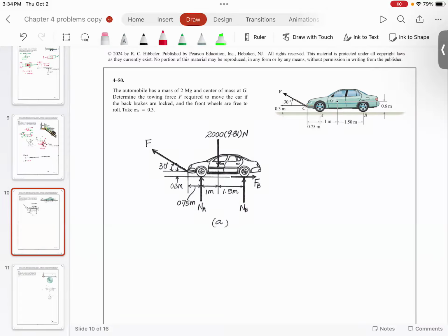And understand, I don't know if you have seen the older vehicles, older cars. There are two types of brakes. One is a disc brake and the other one is a drum brake. Drum brake is like you have a brake drum and you have the brake shoe that clamps the drum. Think like a bicycle brake. Disc brakes are always more efficient. It means the braking power provided by the disc brake is more than the drum brakes because of the geometry. And we'll talk about it.